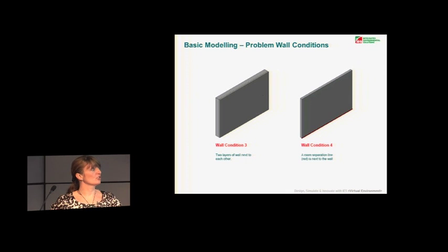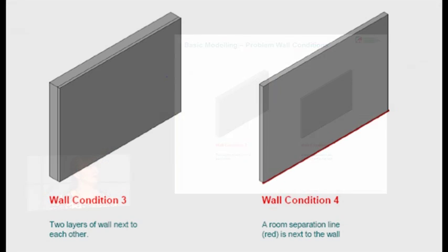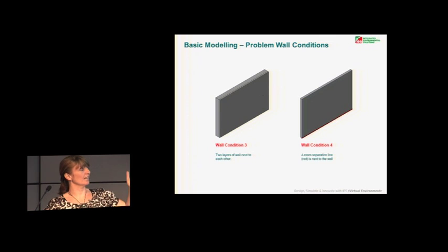Building layers of construction, again, will create the same sort of result. So it will take the inner surface of that to be the wall, and then it will take the external layer to be a shading surface. What we would do there is to set that internal layer to be non-room bounding, okay? We actually define constructions not by building them as individual layers, we just define them by the materials that they're made up of and the thicknesses.